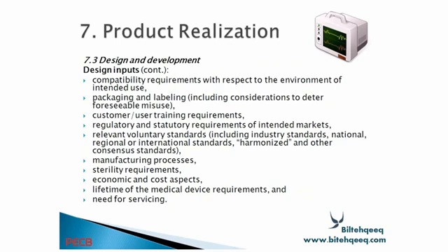Design and design input continuing: compatibility requirements with respect to the environment of intended use, packing and labeling, including consideration of measures to deter forcible misuse, customer user training requirements, regulatory and statutory requirements of intended markets, relevant voluntary standards including industry standards, national, regional or international standards, harmonized and other consensus standards, manufacturing process, sterility requirements, economic and cost aspects, lifetime of the medical device requirements and need for the servicing.